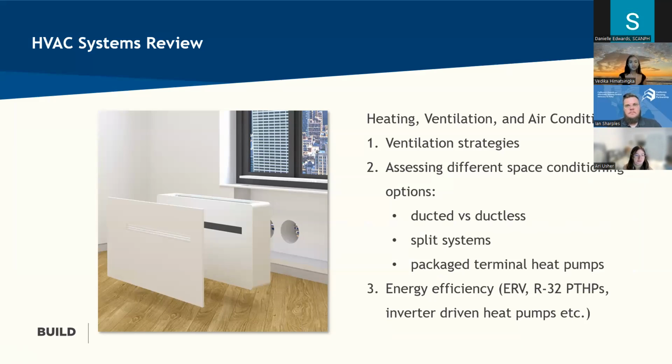So another section of our design review that we spend a great amount of time analyzing is the HVAC section. And one of the first things that we look at are different ventilation strategies. We have seen different project teams take on exhaust or supply only or balanced ventilation strategies. And once we receive the plan sets, we analyze the building as a whole and each individual dwelling unit and determine what the most appropriate ventilation strategy is for the project in general.